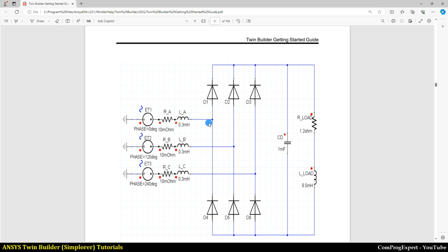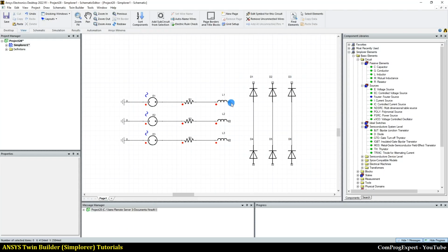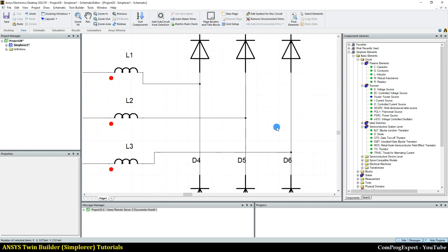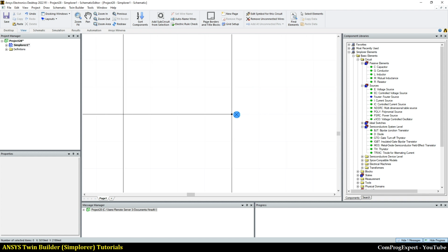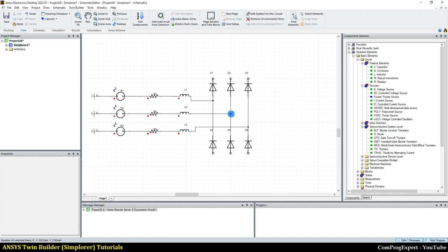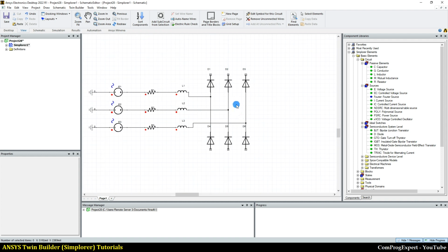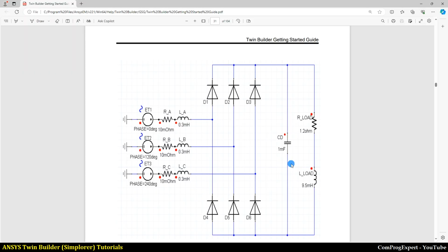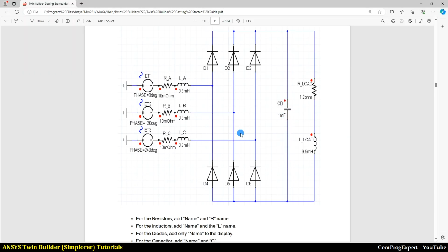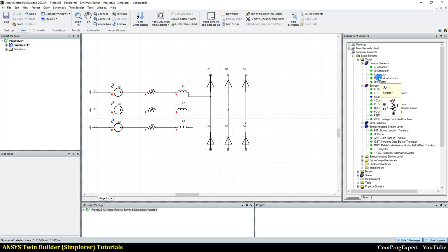This phase is connected to the first line, the second line, and the third line. You know, when we have the correct connection, you should see this dot, the filled circle. So we can make sure that the connection is correct. Then we should place a filter capacitor.